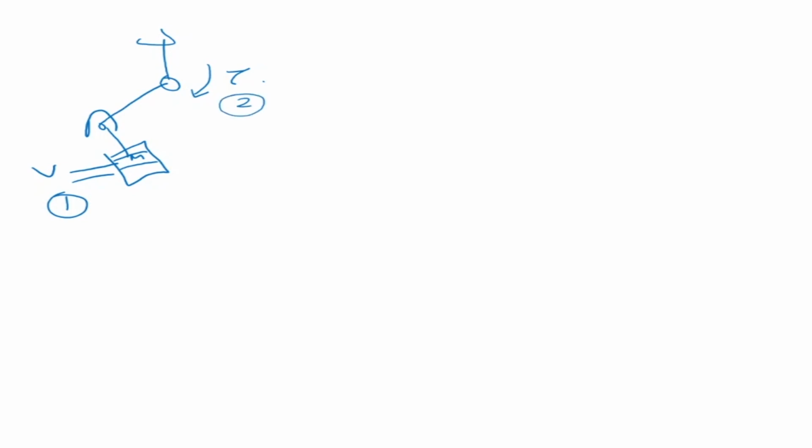so it is extremely difficult to do this in real time. This will be more important for our case in terms of control, because we said that for a robot controller, the dynamics actually disturbs the system. So this robot controller essentially has two inputs. If you have independent joint control, one input is the voltage which is going to the motor, and the second input is the disturbance torque tau which is coming from the dynamics. So this is actually a multi-input, multi-output system, and it's highly nonlinear. And if you want to compute it, we can't do it in real time.